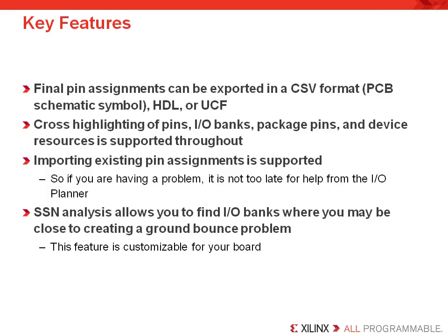You should also know that your final pin assignments can be exported into a CSV format for schematic symbol generation, placed into HDL, or put in UCF syntax. The UCF file can then be loaded into an Excel spreadsheet, and the pin properties can be cross-referenced by their attributes. Some designers find that very valuable. We have also seen from previous slides how cross-highlighting the pins is incorporated throughout the various windows of the I/O